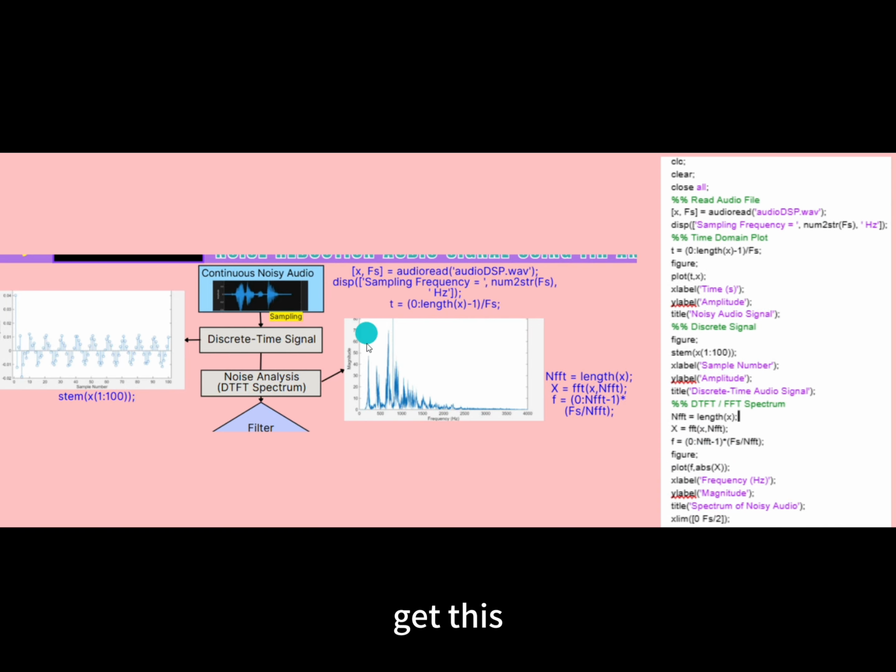So we can get this magnitude against the physical frequency. So by looking at this graph, we can say that the dominance is below 1000 Hertz. So from here, we can directly inform the cutoff boundary we need to set for our FIR filter design.